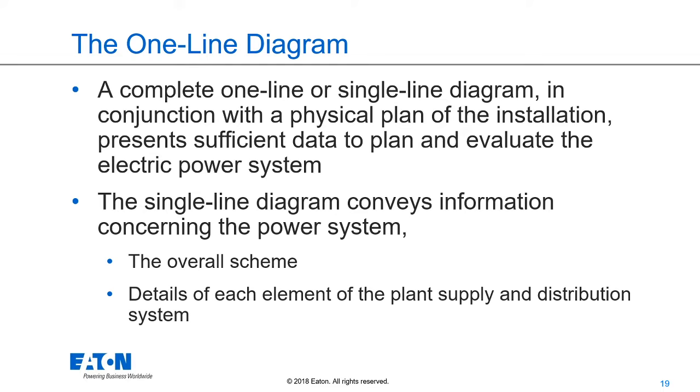But if you're doing short circuit studies or selective coordination studies, and you don't want to be the most expensive guy on the block when you put in your bid, you're going to want to make some estimates on conductor lengths, because if you go too long on a conductor in the planning phase and the actual as-built drawings say that the conductor is shorter, you know that a shorter conductor will give you higher fault currents. That may have led you to pick the wrong equipment, either from a selective coordination perspective or from a perspective of interrupting ratings of overcurrent devices or short circuit current ratings. So you want to be conservatively short on your conductor lengths, but you may be able to use the plan views to figure out how far away your equipment is from each other.